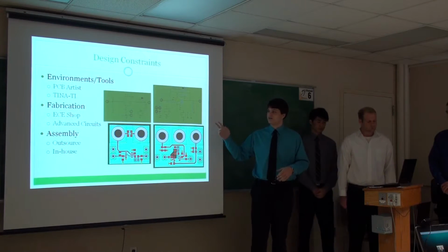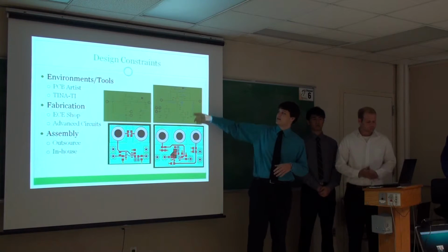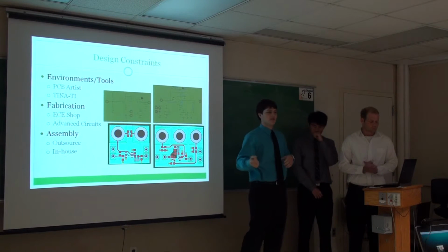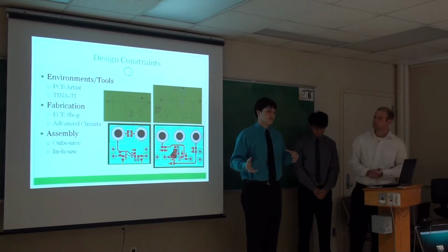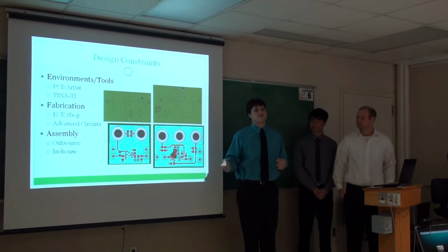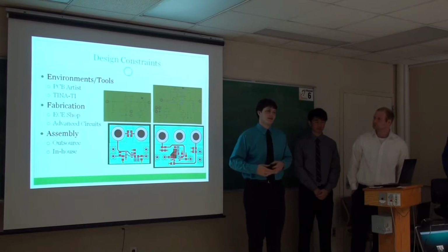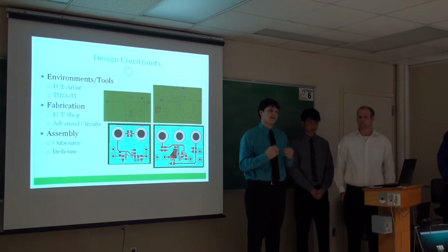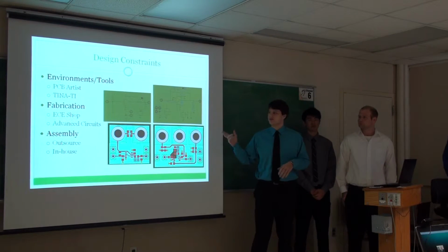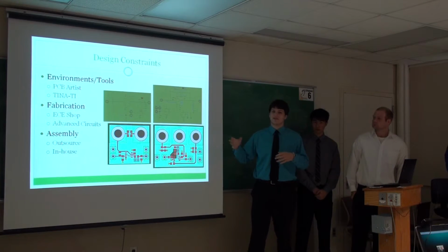These two are stability circuits for demonstration. As you can see, these black dots are switches, and when the switch is open, it'll oscillate because non-ideal op amps, which are the only thing we have in the real world, can't drive capacitive loads very well. And the same thing's true with a high input or high impedance feedback. It doesn't work very well. So these two samples are just some things that we'll be putting together to practice.